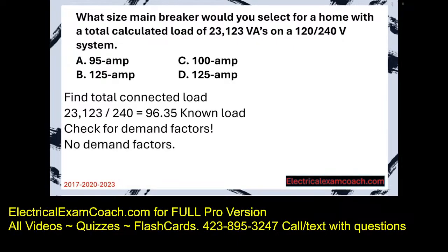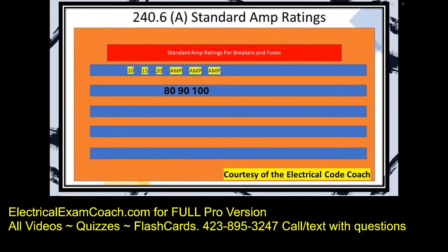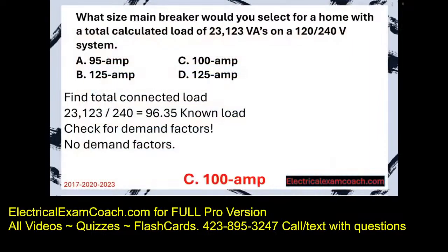Now that we have our known load, we head to table 240.6a, and we choose the next size up. And in this case is going to be a 100. Great job.